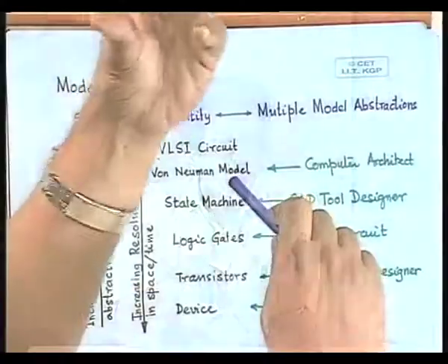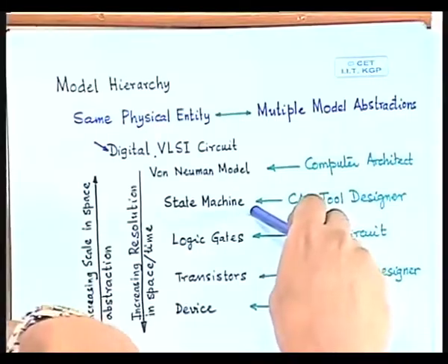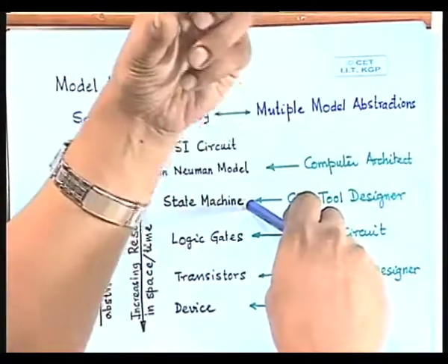So you may come down to small computing units which are combined in a particular way. That is called the Harvard architecture. Well, how are they made? So if you ask, somebody will say, how does it function? What is its behavior? Each module. For example, one of the important components in a signal processor is the multiplier. That's why signal processors are so fast, because they have a hardware multiplier. So how does the multiplier function? What is its behavior?